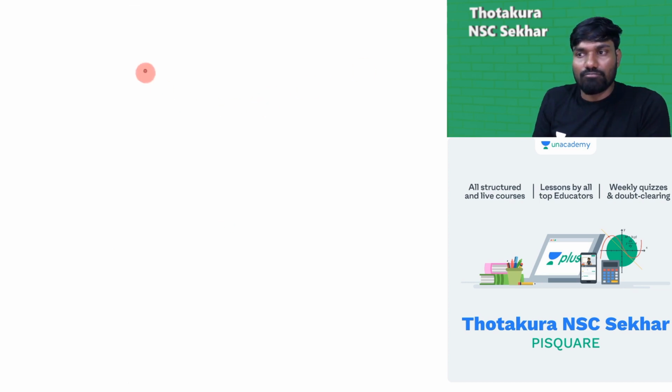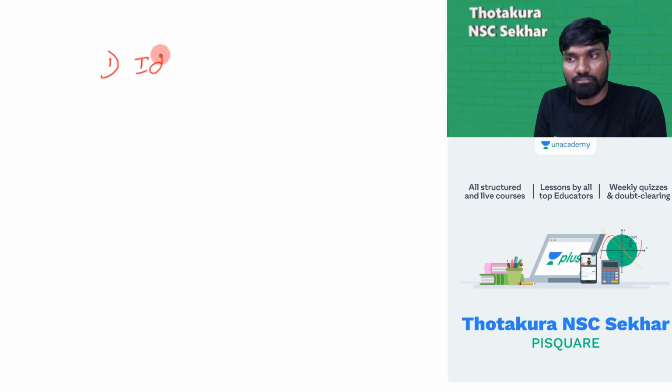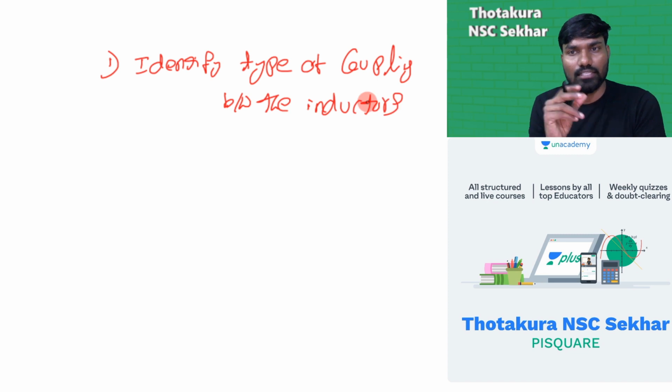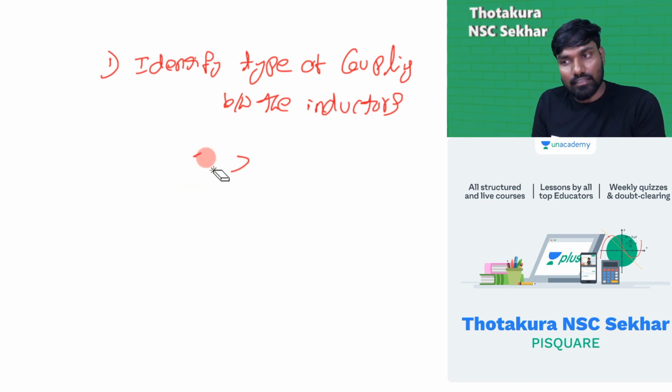First step is, for every coupling, any type of coupling you have, identify the type of coupling between the inductors. That's the first thing you're supposed to do. If it is positive coupling, write there plus next to the arrow. If it is negative coupling, write there minus. Then that will be easier. That's the first one.